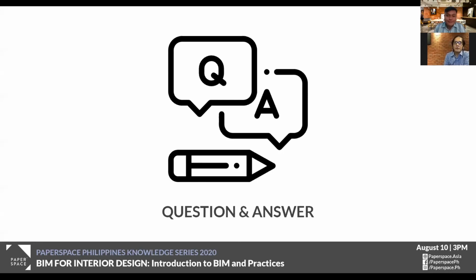Probably I would suggest, if that's the case, try to export it in a different format. So probably look in the SketchUp. Check on the other options that you can use. If it is having that kind of issue still, probably I suggest you can try to export that into a CAD file or a different platform, or work your way around to Revit, because there are some cases that the model tends to explode sometimes.